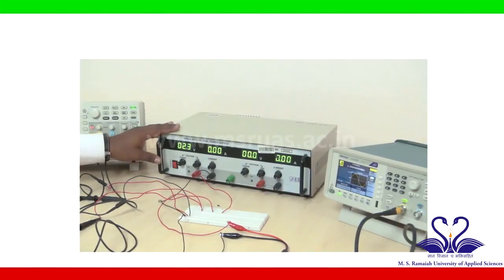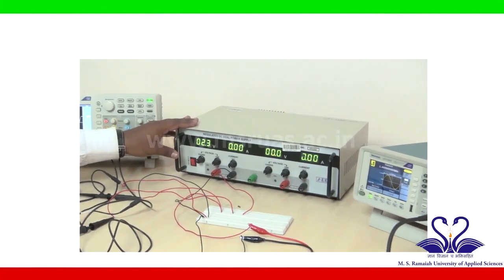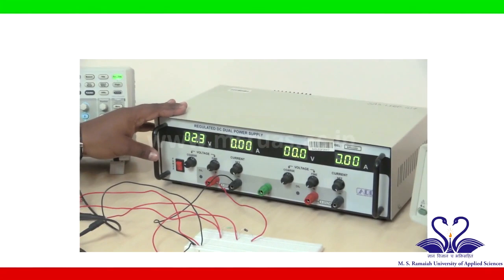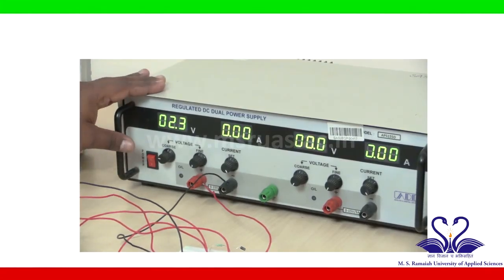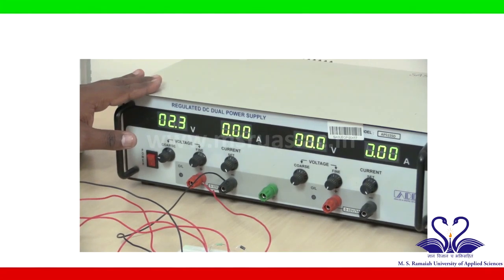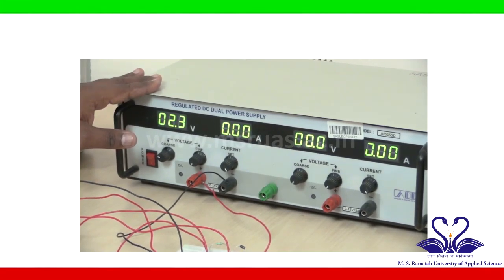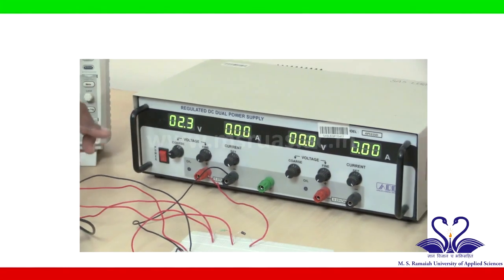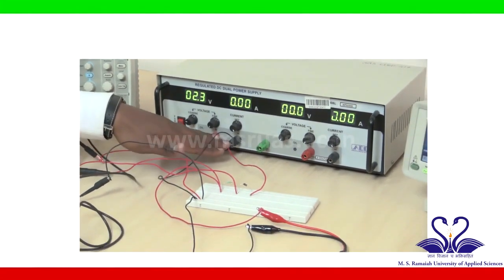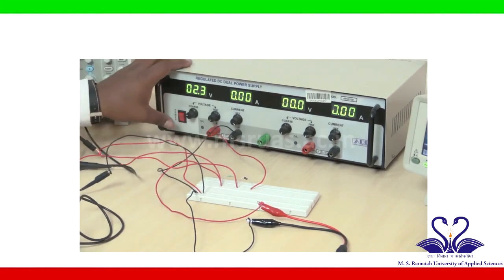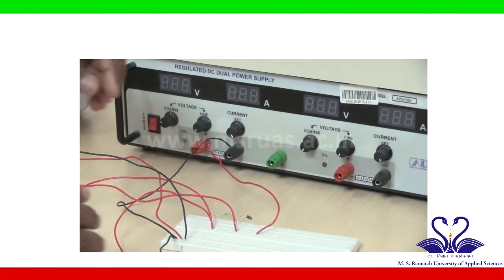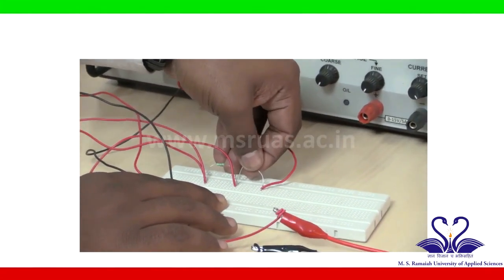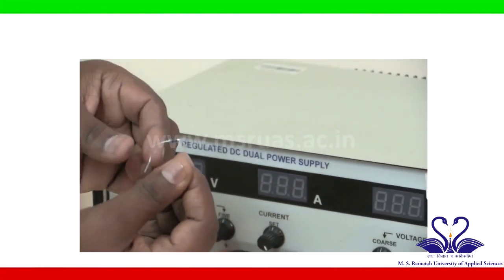Now we have finished the positive shunt clipper circuit and we have obtained a clipping level of plus 3 volt. Now we will start with the negative shunt clipper circuit connections. If you see the circuit connections of the positive shunt clipper and negative shunt clipper, there is a very small difference, that is the diode direction has been reversed and the DC voltage source terminals have been reversed. So before doing this, I will turn off the DC dual power supply, and I will remove the diode and connect it in a reverse direction.